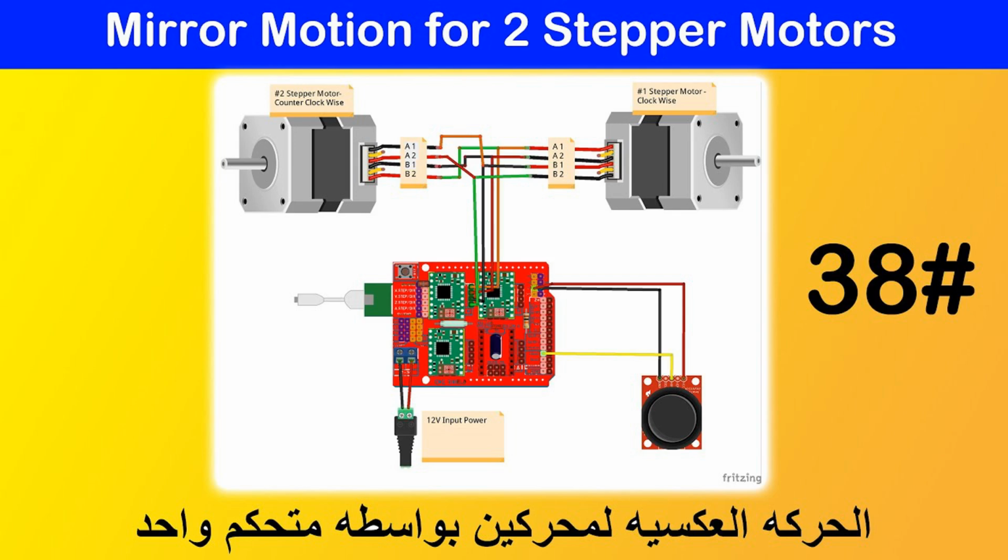Operation: in half-step mode, the motor alternates between a full step and a half-step, providing smoother motion compared to full-step mode. Applications: full-step and half-step drivers are used in applications that don't require the fine resolution of micro-stepping, but where efficiency and basic control are more important. Examples: many basic stepper drivers, including the L298 full-step or the A4988 half-step.